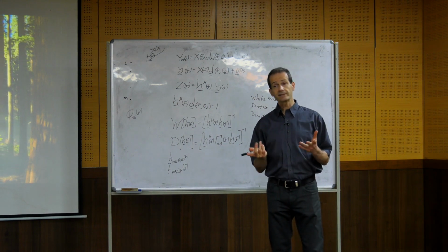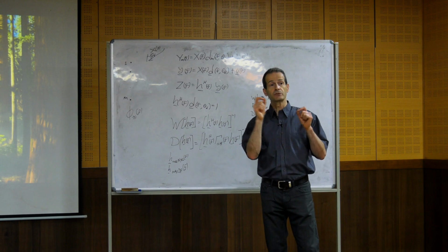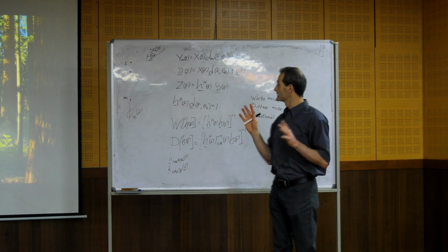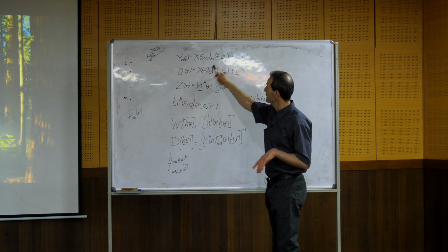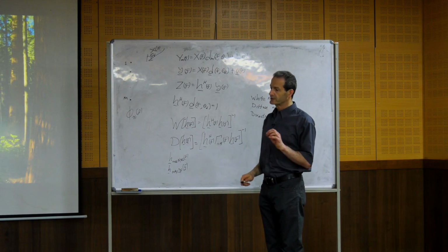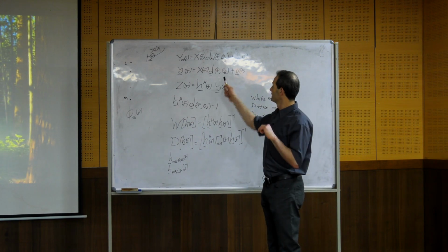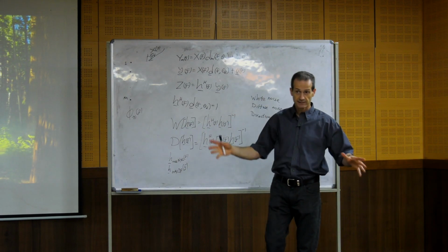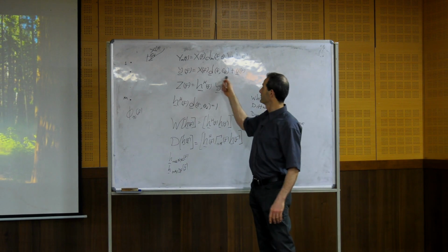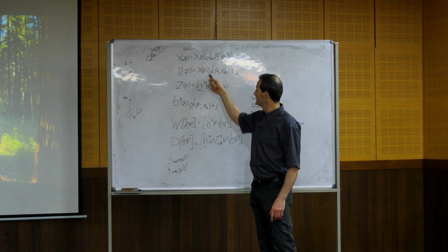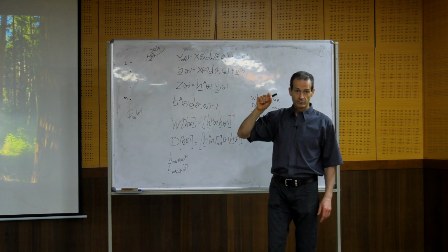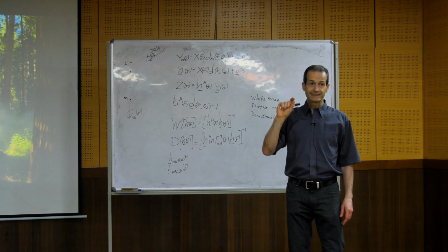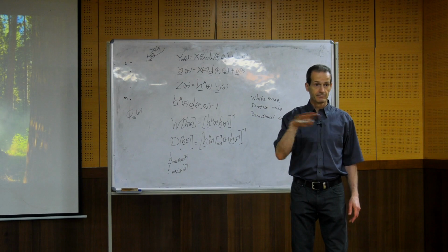We need also robustness to inaccuracies in the position of the sensors, because we assume, when we take the steering vector, that we know exactly theta d, and we know exactly the positions of the sensors in space. Because if we don't know, then it's incorrect. This steering vector needs the position of the sensors in space. And we also assume that the sensitivity of each sensor is the same.